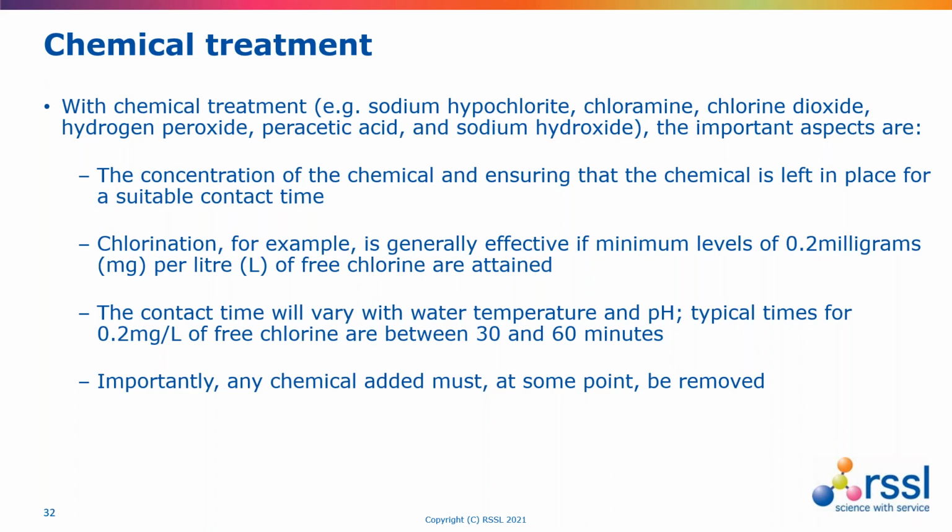And the important point here is the concentration of the chemical and ensuring that the chemical is left in place for a suitable contact time, and also balancing that off with the risk of corrosion that could occur. And the concentration of chemical depends upon the length of the water system and the flow rate. But for example, if we're seeking to chlorinate, then we start to get effective levels of active